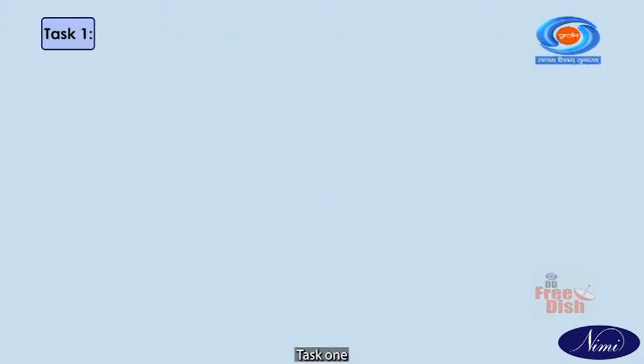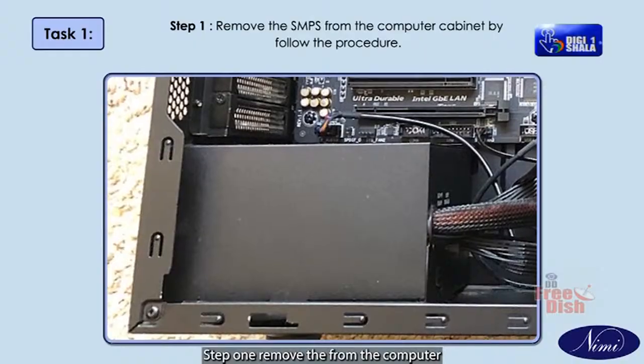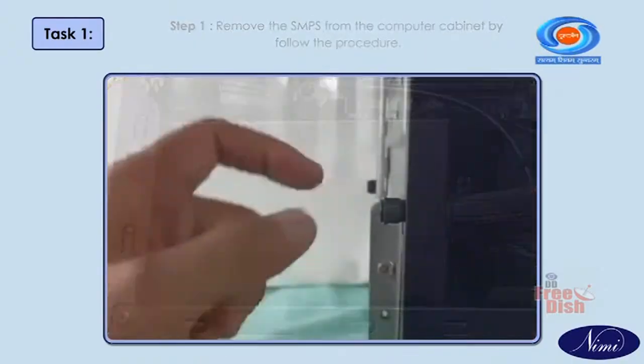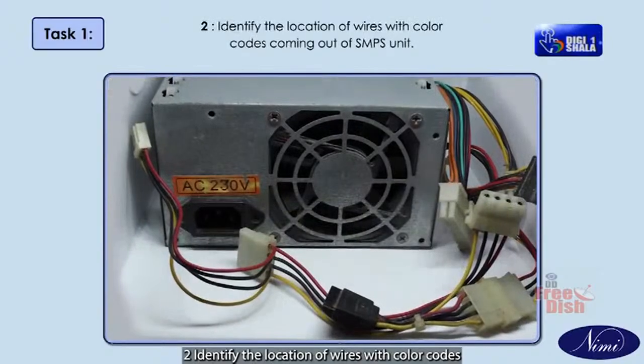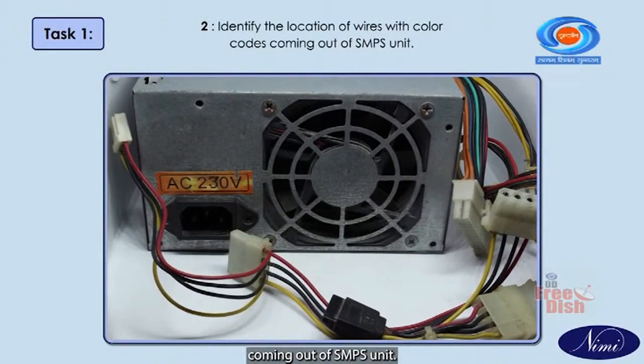Procedure. Task 1. Preparation of computer SMPS unit for voltage measurements. Step 1. Remove the SMPS from the computer cabinet by following the procedure. 1. Open the computer cabinet cover by removing the door screws. 2. Identify the location of wires with color codes coming out of the SMPS unit.